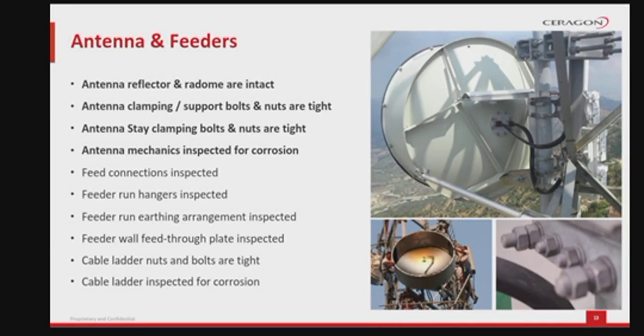During the physical verification of the components, check the integrity of the radiation system, including antenna support, the antenna's radome, and the clamping system. Check that there is no trace of corrosion on any of those parts. In case physical damage of any component is detected, take a note in order to plan a future corrective maintenance activity.